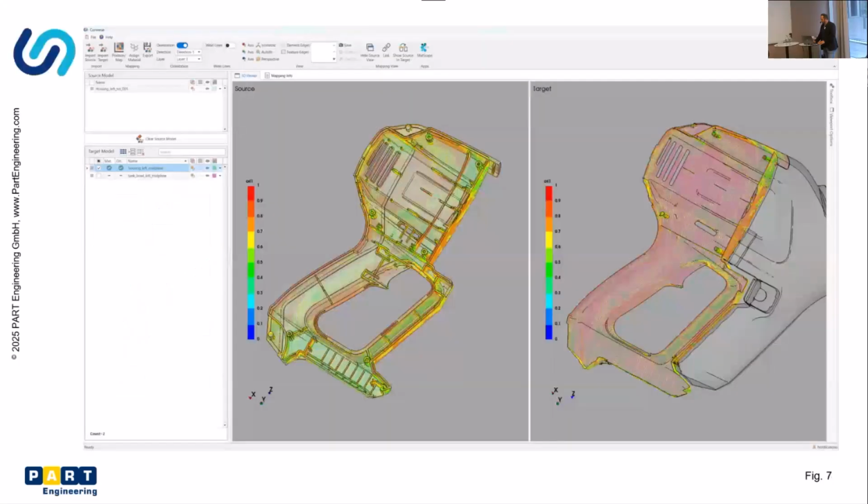So coming to the first part, how to consider that. As I already mentioned, luckily injection molding solvers, such as, for example, in the Altair world, Inspire Mold, or with the APA, the Altair Partner Alliance, also the partner software Moldex3D, can be used to predict such fiber orientation. And then there are possibilities such as ours, for example, to assign such orientation to your mesh.